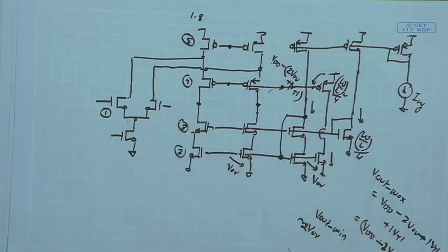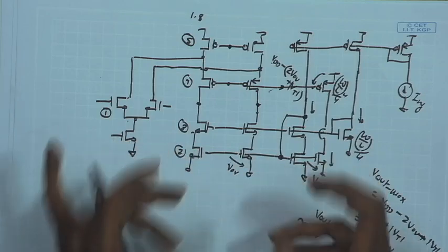Now, another question that I would like to ask about the common mode feedback: whether to use a PMOS load and NMOS input device, or to use an NMOS load and PMOS input device.